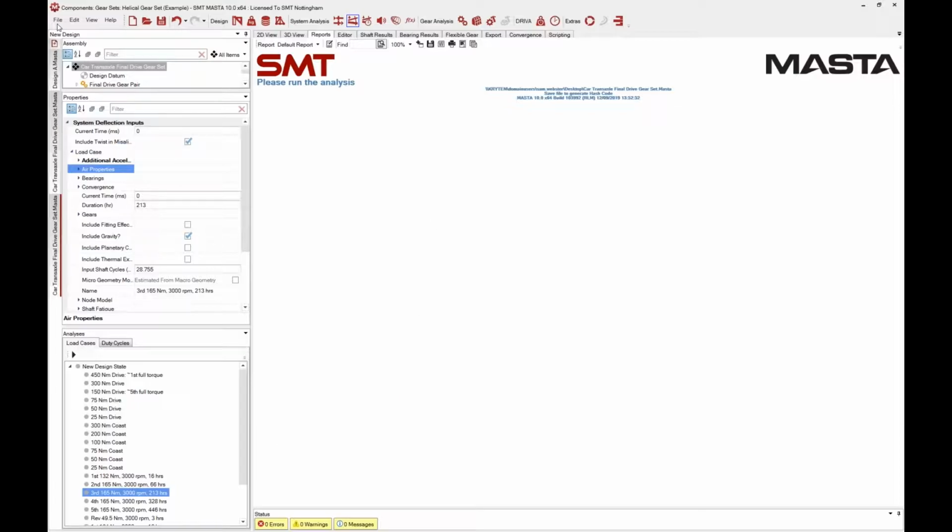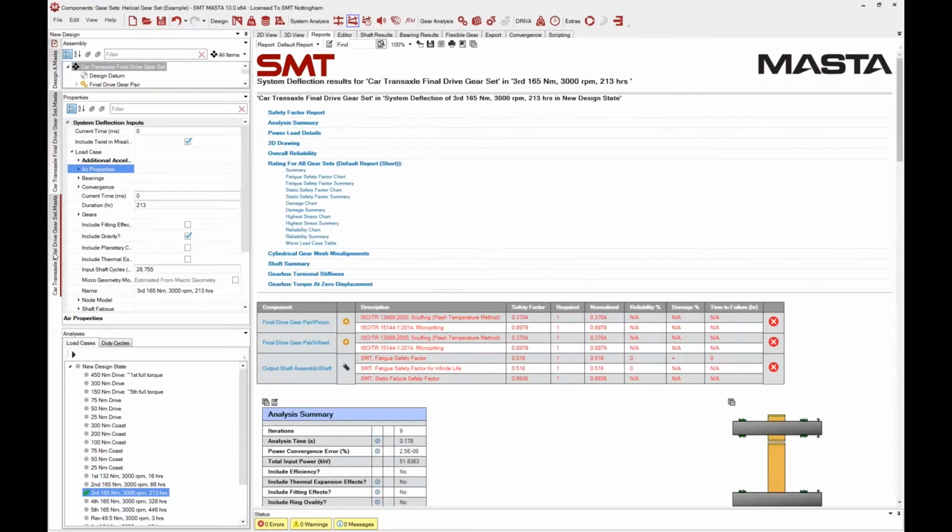And then the last thing, which I've kind of been doing anyway, is the ability to duplicate designs. So if you wanted to do some direct comparison between alternate designs, for example, you could open up different iterations of the design along this ribbon on the left-hand side. So let's say, for example, I wanted to run this load case through and do a comparison with another slightly different model.